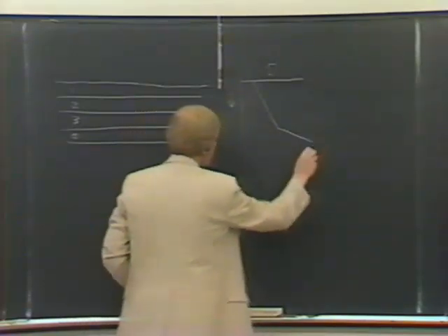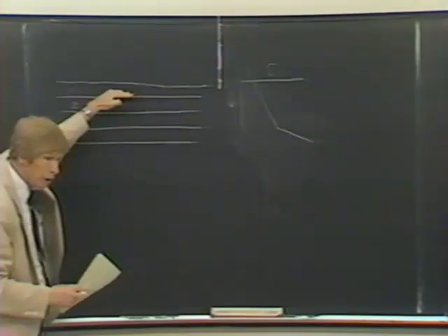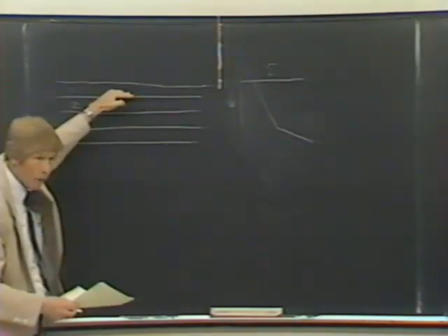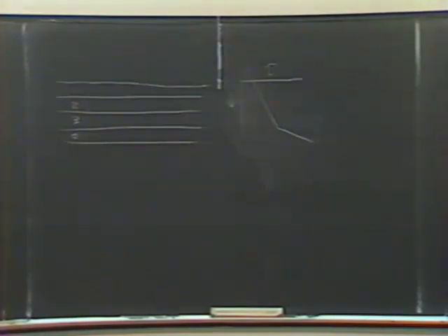But if it's for a short time only, that is just during the slack water, then using a linear increase isn't too bad. So what will happen is that if it's an area of deposition, you may have 4 layers deposit during slack water and 3 of them wiped off. And then the next time you have another 4 layers, another layer up here, and 3 of them wiped off again, so that you actually get deposition.